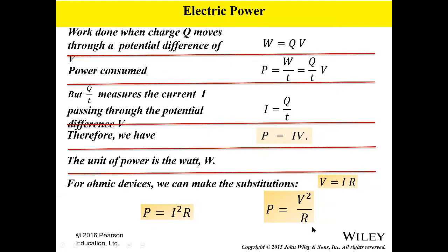So if you, for example, have a hairdryer and you bring your hairdryer because you're going on a trip to Paris or to Amsterdam, Netherlands, you then will bring your hairdryer that already has a resistance that doesn't change. But when you go overseas, the voltage is double what is in this country. Therefore, the power used on the hairdryer now is 4 times.